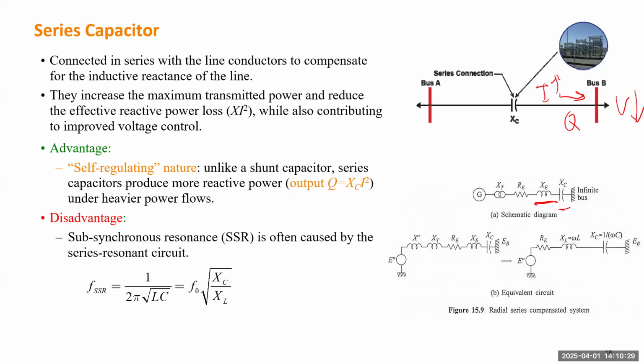So you are going to generate a resonating circuit, and this circuit will generate a resonance frequency based on the formula. L will be the total inductance along the transmission path, C will be the total capacitance of the transmission path. If you want to use the impedance of the line and the impedance of the capacitor, we can also use this formula. So f0 is 60 Hertz.